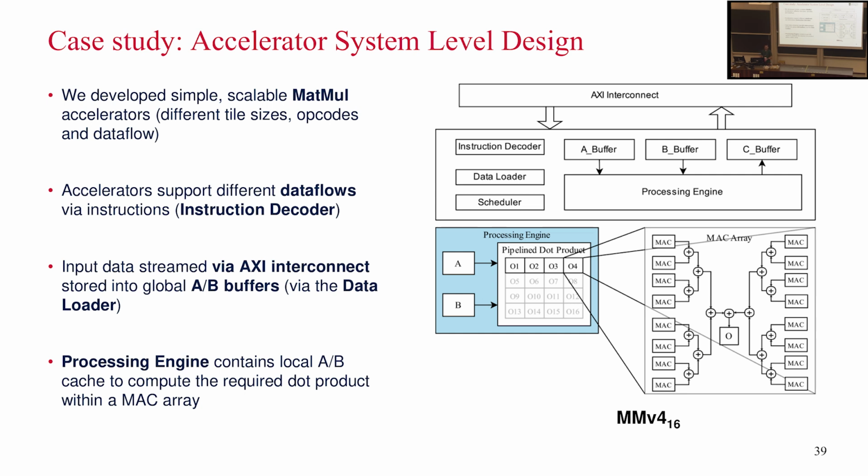We designed a family of MatMul accelerators based on different parameters: the tile sizes, the opcodes, and the data flow. The idea is that we use different data flows: input stationary, output stationary, no data flow at all, and different sizes. This is what we did. The accelerator itself is based on a MAC array, and there are a bunch of buffers to put the input matrices. Obviously, this accelerator is for matrix multiplication only, not full models.